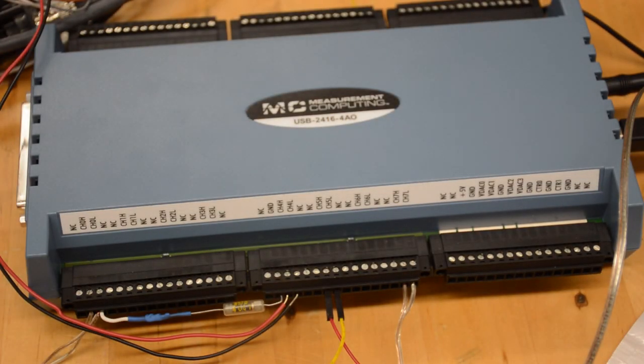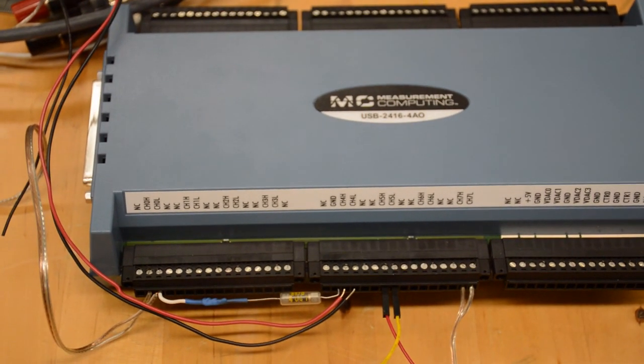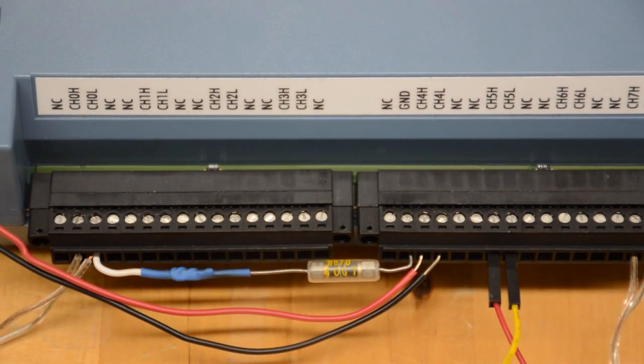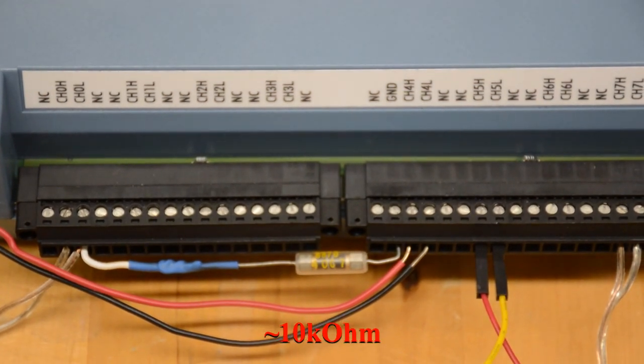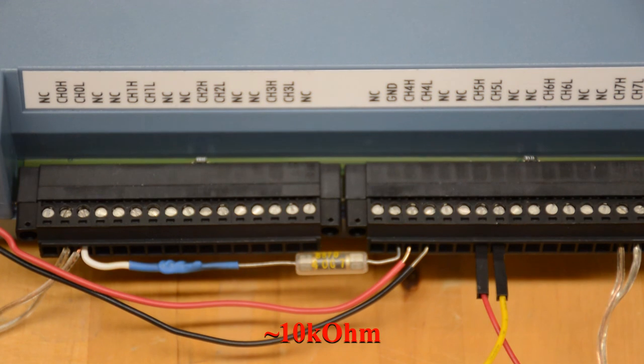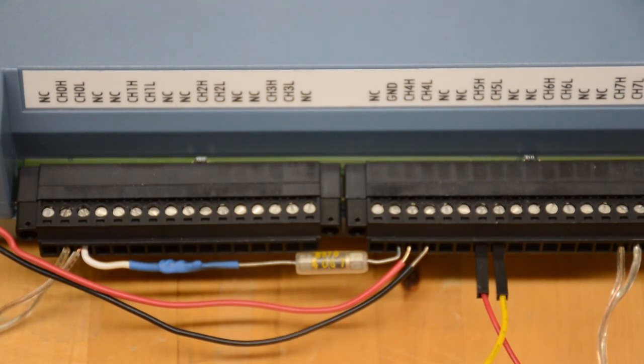One important thing to remember is to always connect your sensor to the active channel. If you activate a channel in the software, please connect the sensor to the inputs. Otherwise, your setup will get junk from the non-connected points. And one last thing is choose one of your active channels and connect a resistor between the channel low and the ground of the instrument. The ground is here. This will ensure that the ground of the entire acquisition setup will be maintained throughout the test.